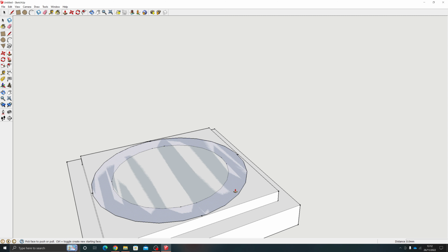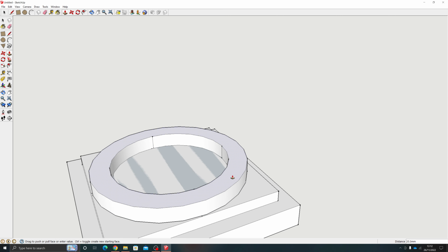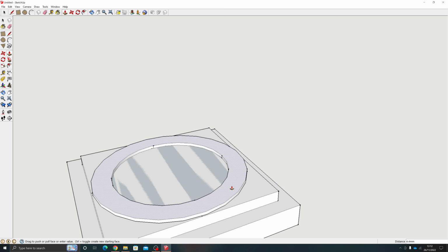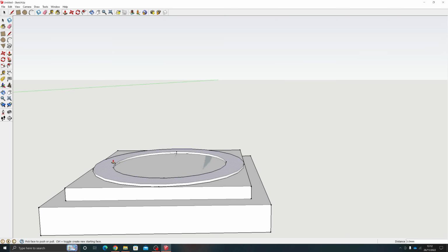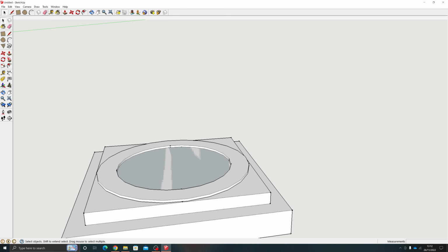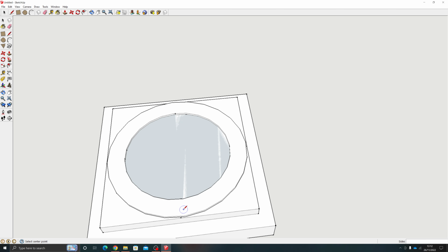And just move that up like so. Because you're using acrylic, and the acrylic we'll be using is 3mm thick, I'll set that to 3mm. Again, it just helps you visualize it. Now I need to think about how I'm going to have my acrylic held together. So I'm actually going to have separate poles or rods that are going to go up.